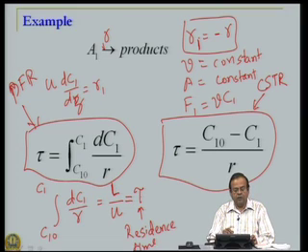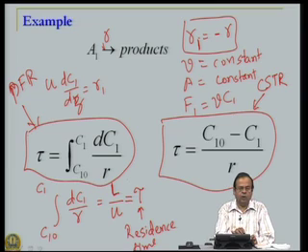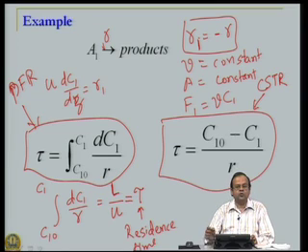It means we have the same residence time in a plug flow reactor and a stirred tank reactor. Which of these two reactors gives us higher conversion of A1? That is one way of comparing, and whichever gives higher conversion is the better of the two reactors.